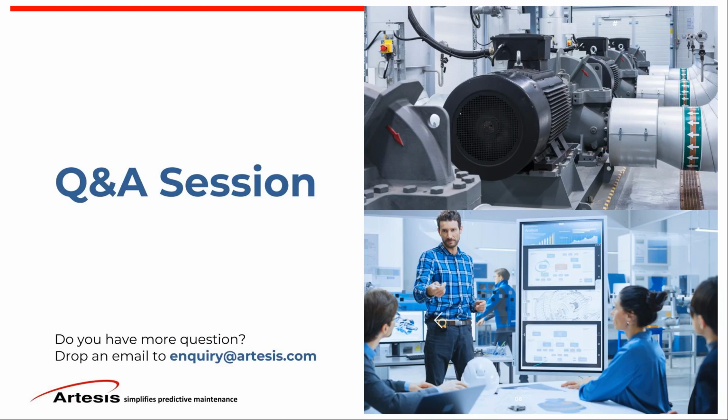If the motor is on and off periodically, such as a chiller, yes. So basically the question is, if the motor is not constantly running and runs on and off periodically, it won't affect the MCM's ability to learn it. However, it will affect the duration, so it will take longer. It will start learning or continue learning when it's on. If it's off, it will pause and wait and resume when it's on again.